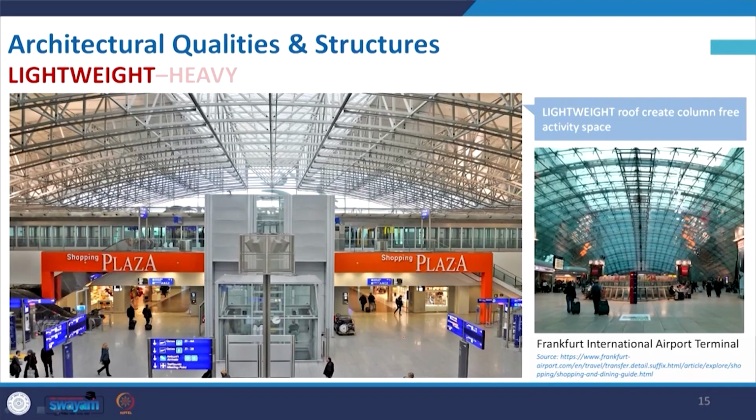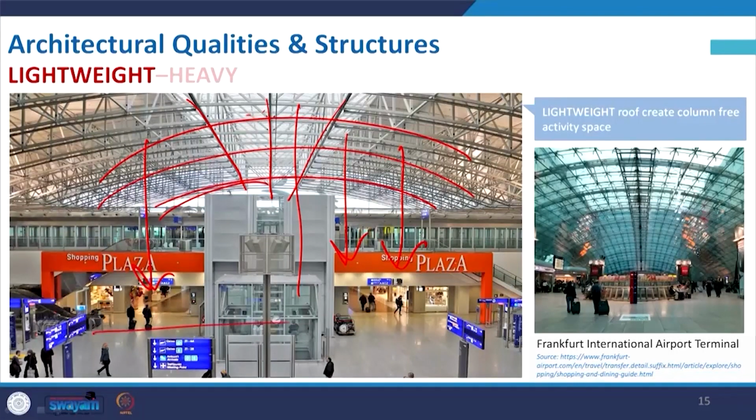Otherwise, we have to make the roofing very light. So, for that truss can be used, space frame can be used. These are the structural elements where small dimension or small cross section of the iron members can hold this, and along with that advantage, you can create some translucent environment which will allow light to pass on, so that you can also maximize the daylight use.